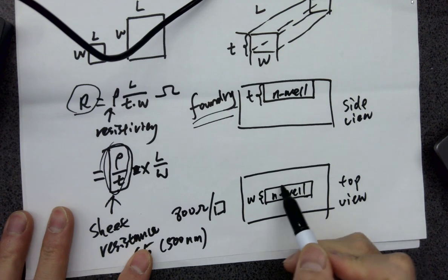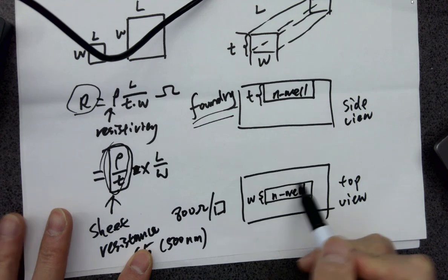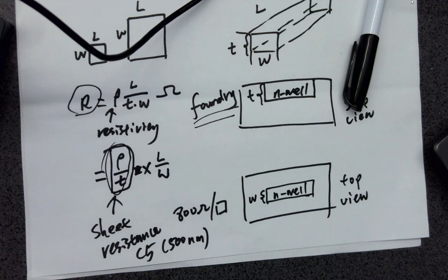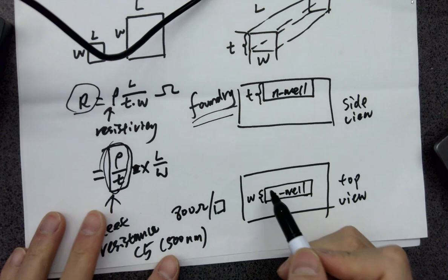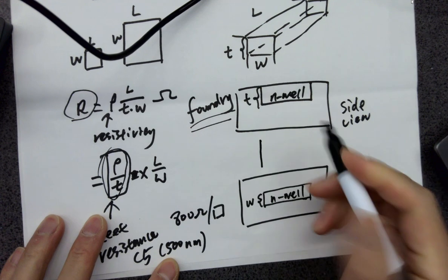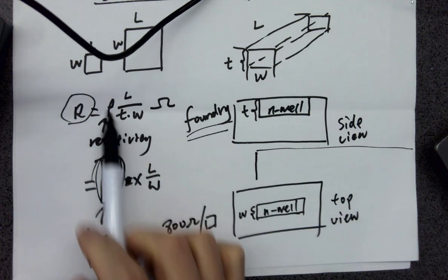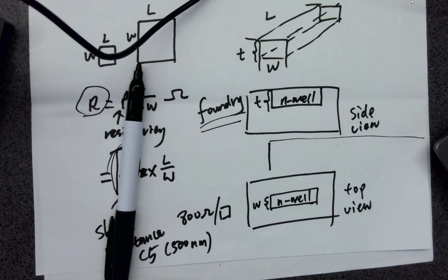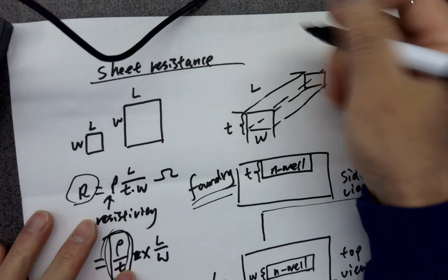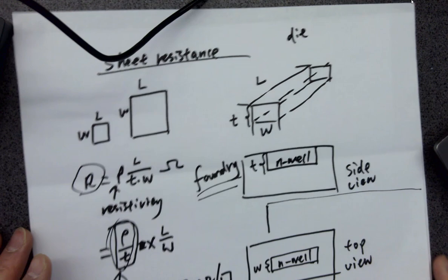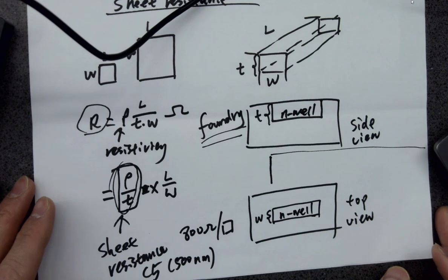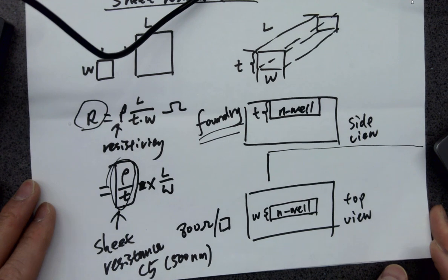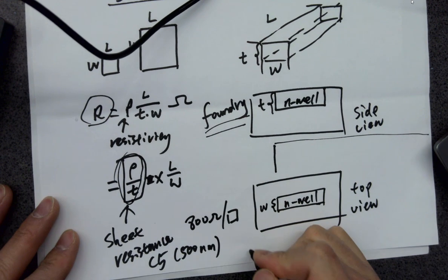So when you are laying out a resistor, you want to pick the minimum W, so you can use the minimum dimension extended in the dimension of the length to form a certain value of the resistor. If you double your width, you need to double your length as well to realize the same resistance, which takes a lot of area on the die. You have limited area on the die, which is the wafer, the chip, die. So you want to reduce the footprint of every single component as much as possible to save money. Any question on this?